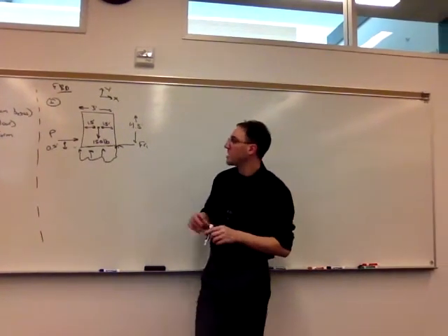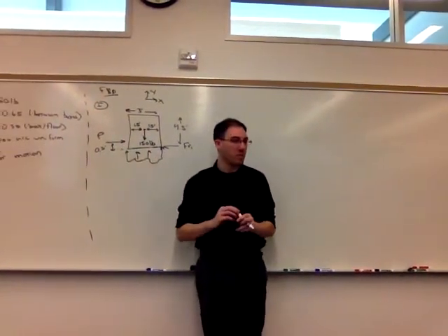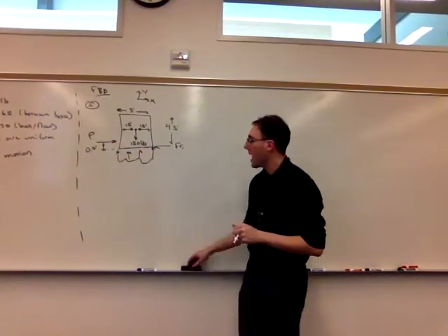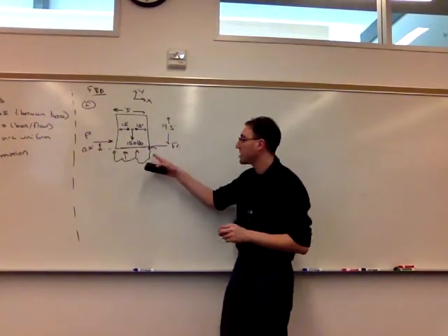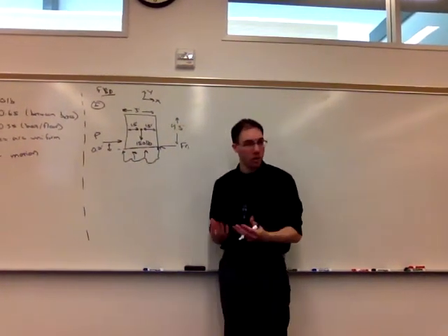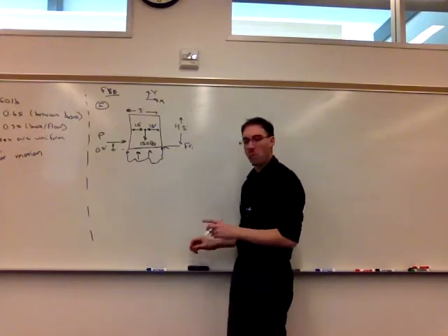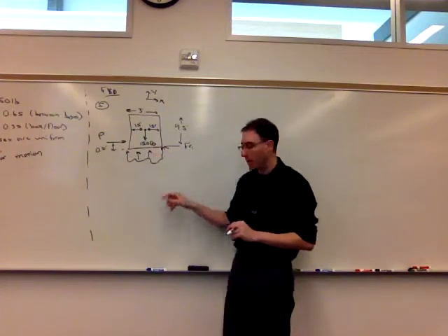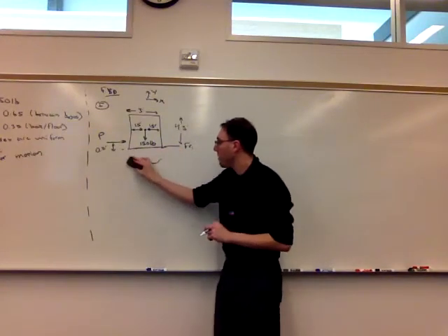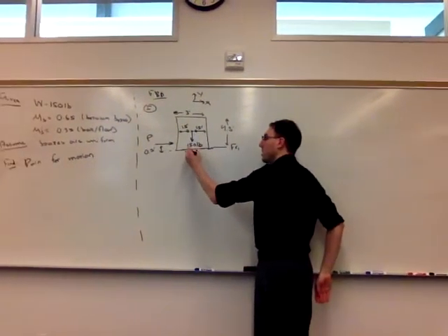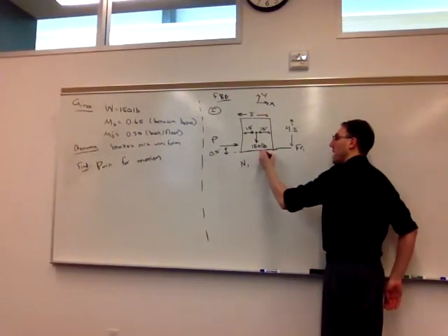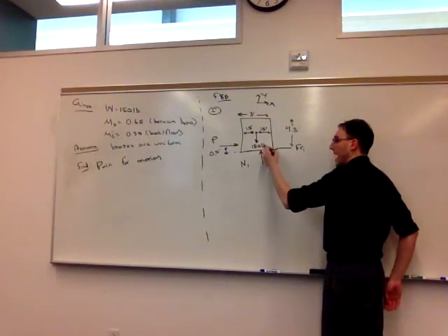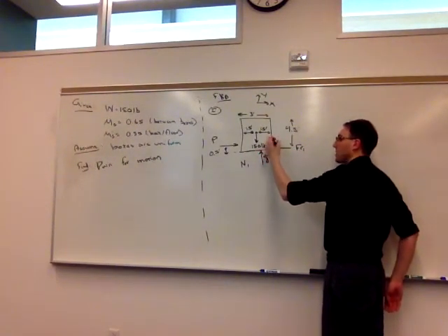We only can make that assumption if we were not applying a force P. So we can't make that assumption. But what we can say is this distributed load has some equivalent load that we call the normal force, and it acts at some equivalent location, which would be the centroid of this distributed load. So I'm not going to model it as the distributed load. So some value N1, and I don't know where it is yet, but I'll be able to figure that out.